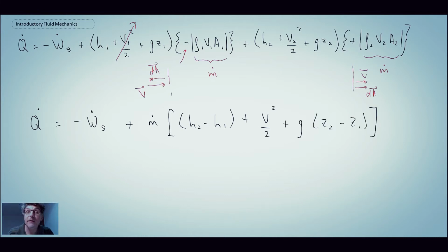So it looks a lot like what you get in thermodynamics. It is the system formulation, or the expression, not for a fixed mass, but for a control volume of the first law where you have mass crossing the boundaries. We did say that the potential energy did not change, so that term disappears. We have H2 minus H1. How do we deal with that?